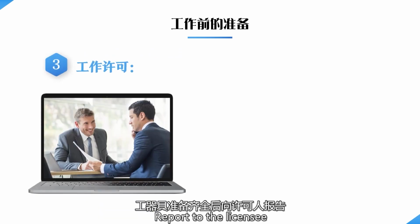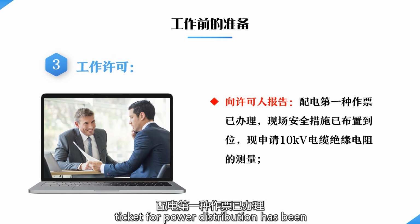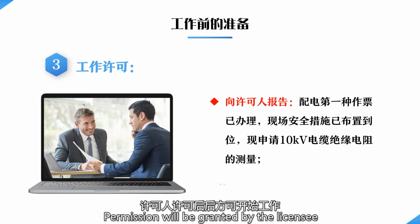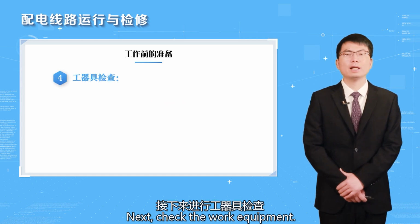Report to the licensee when the work equipment is ready. The first operation ticket for power distribution has been processed. Site safety measures have been arranged in place. Now apply for 10 kV cable insulation resistance measurement. Permission will be granted by the licensee before starting the work. Next, check the work equipment.